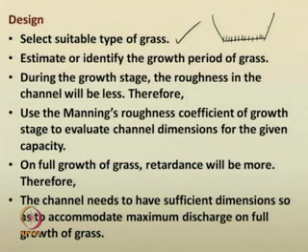We have seen earlier how Manning's roughness coefficient varies with the type of grass, the growth of the grass, and the height of the grass. So, you have to use the appropriate Manning's roughness coefficient, and you will see that it changes with respect to the growth of the grass. The Manning's roughness coefficient according to the growth stage has to be evaluated for the suitable dimension.